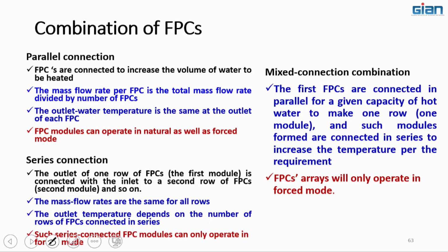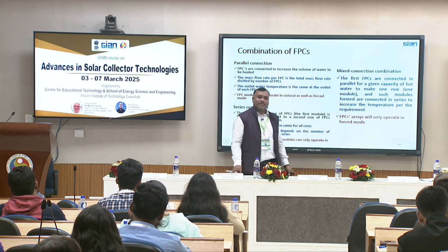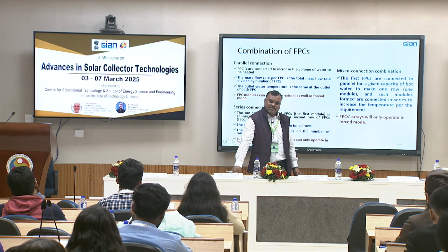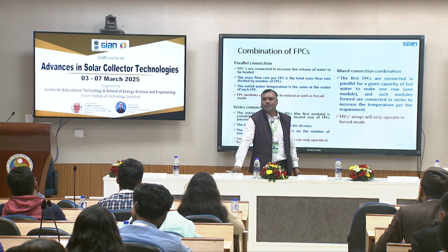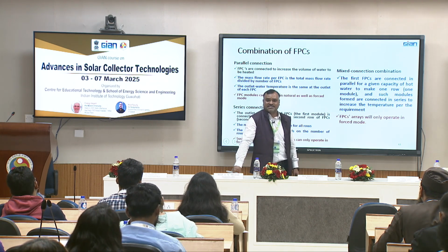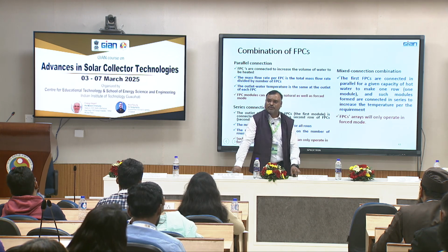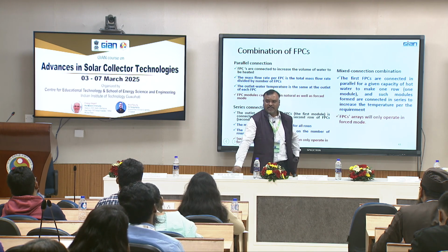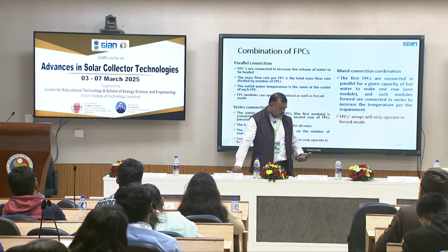And also these flat plate collectors can be connected in series, parallel and mixed. Suppose you stay in a hostel of capacity 1000, and I ask you to design a flat plate collector, how will you design? What is the design basis? First, you need to know the amount of heat to be given, and then at what temperature.